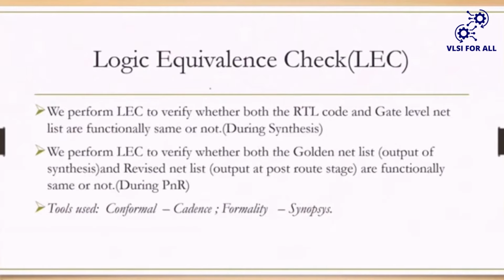But remember team, logic equivalence check is a mandatory check at every stage, which can be considered a sign-off check. If someone asks you, synthesis has been done, what are the sign-off checks? Then please include this logic equivalence check. If someone asks what the sign-off checks after PNR are, tell them the techniques we have to perform after PNR, but include this LEC as well.